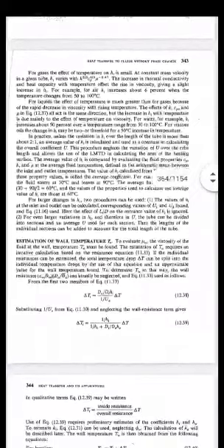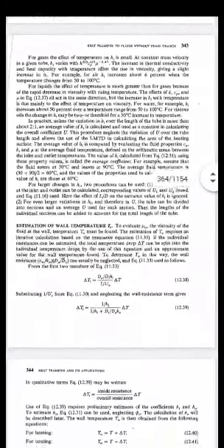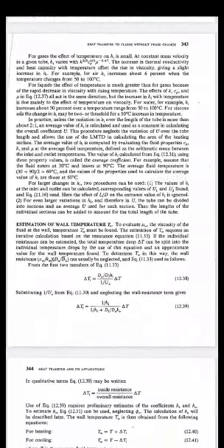So similarly, the estimation of wall temperature Tw. As we are aware, Tw is nothing but the wall temperature. To evaluate mu w, the viscosity of the fluid at wall, the temperature Tw must be found. That estimation of Tw requires iterative calculations, which are based upon the resistance equation we have already seen.